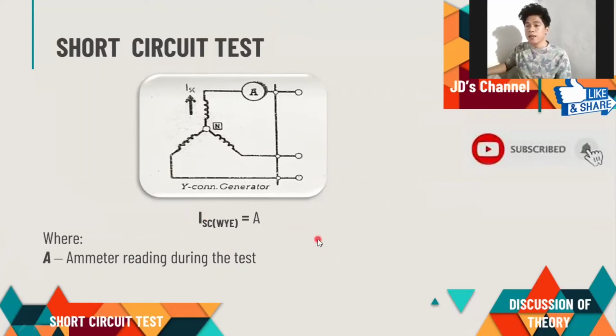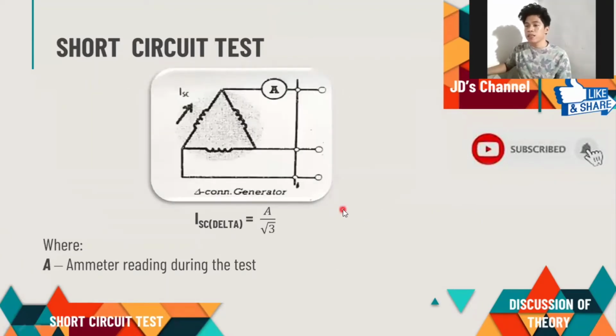And then, if it is Y connected, take note class that this formula is applicable only in Y connected generator. And this one is in delta. So we have the reading of the ammeter over square root of 3. So that is the value of our short circuit current in delta connected generator.